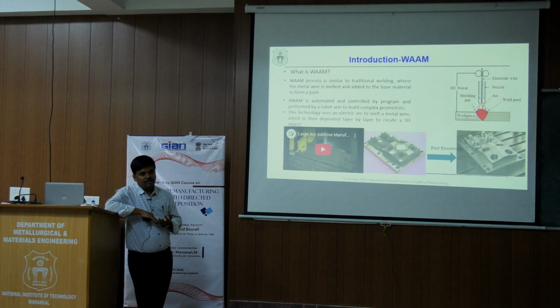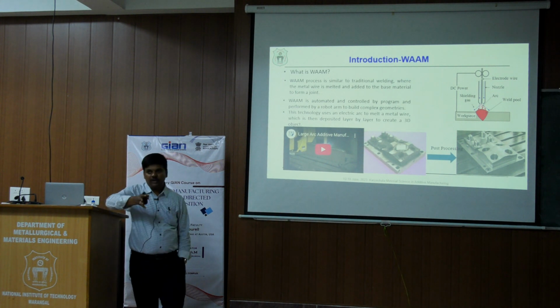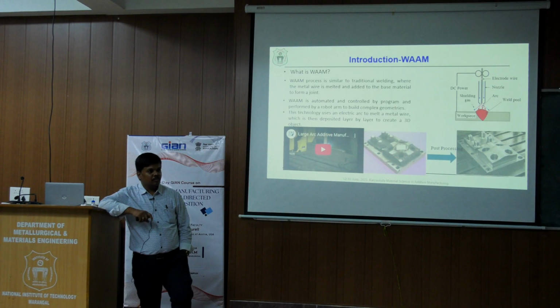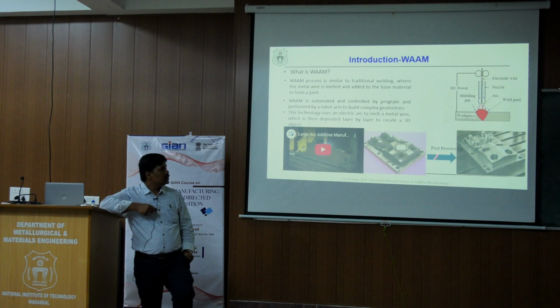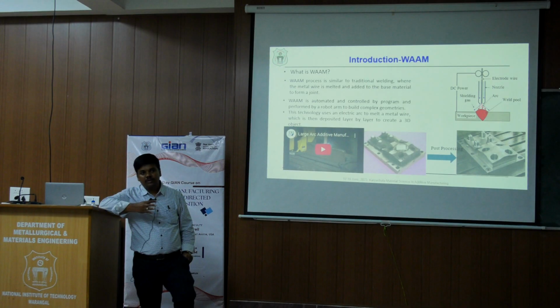You have to compare the efficiency and the quality, especially in the die industry. Lasers we can use for both wire as well as powder. But when you go with powder, complete repairing of that part is difficult, and it is also more expensive compared with wire arc based manufacturing or with the laser based wire DED process.